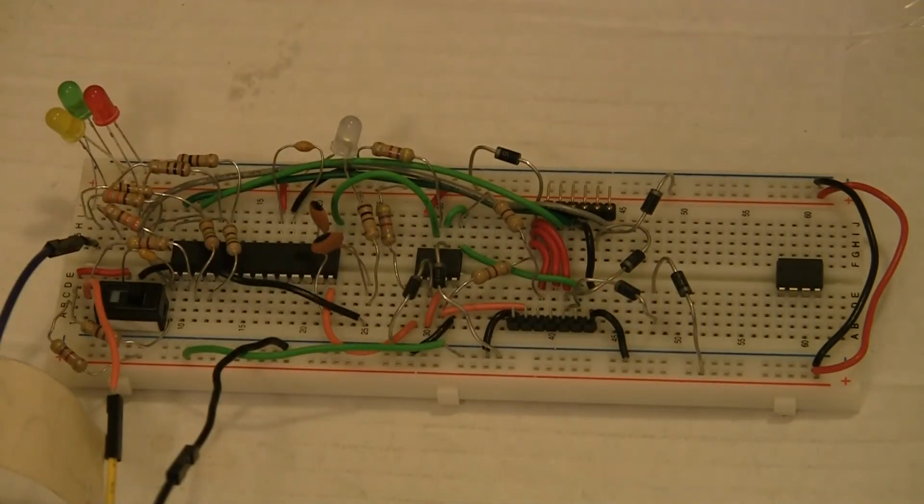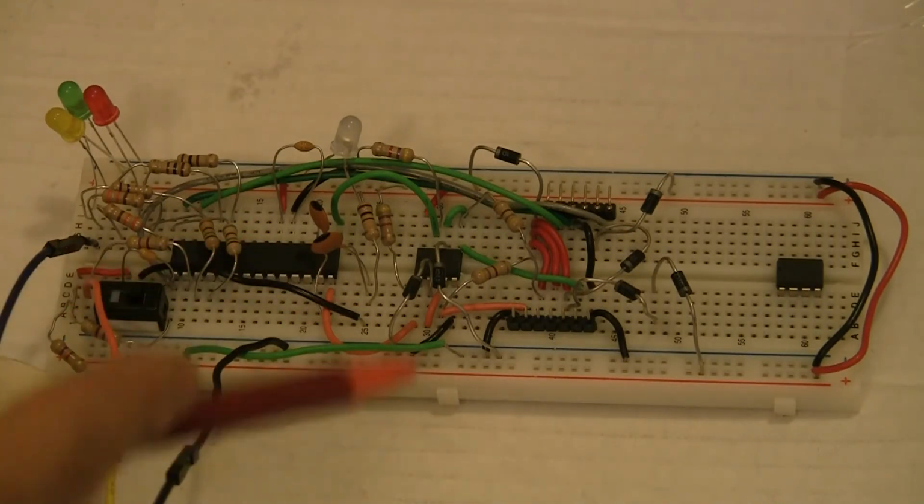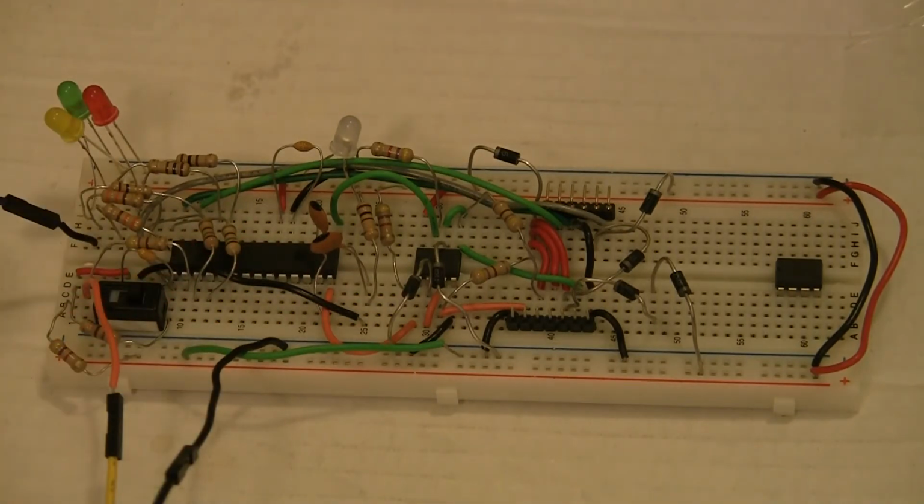The I2C train was working properly at some point, but it could not be reliably tested or verified due to some issues with the I2C ribbon cable and just some wiring issues. After much debugging and looking through schematics and my own wiring on the prototype PIC, I was able to get everything to work properly at the same time, and from there it was just a matter of adding some wires to identify the channels that we would use for reading the IR sensors and the RFID sensors.